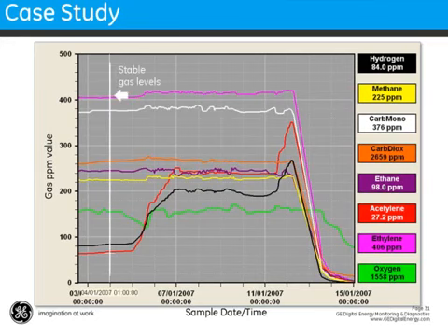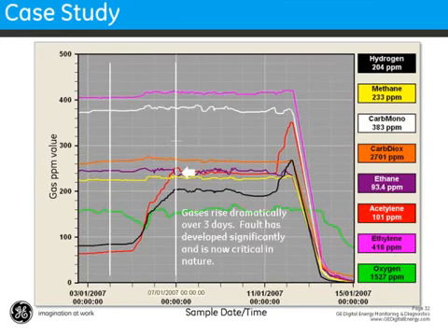And it shows that for the period of time, the gas levels were stable. There's historical data that goes back a long time and shows a long period of stability. Then the gases rise pretty dramatically. Not all gases, but you can see in particular that acetylene and hydrogen are rising. So the fault has developed significantly in a short period of time.